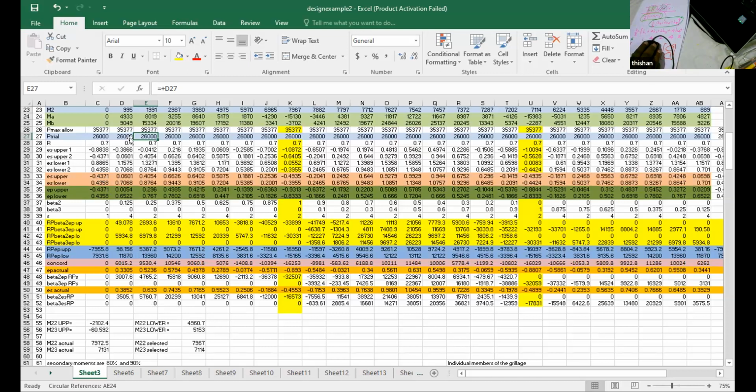And the moment we select a pre-stressing force, we should do this additional check where we see whether, when we fit a cable at the upper limit of line of thrust, at each support we should get a minus answer. When you fit it at the lower limit, at each support we should get a positive answer.